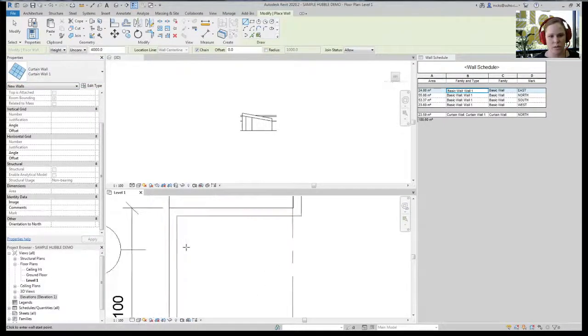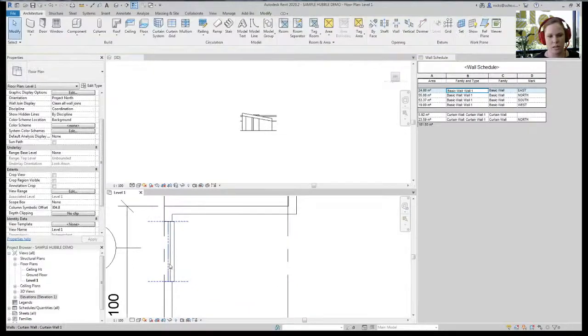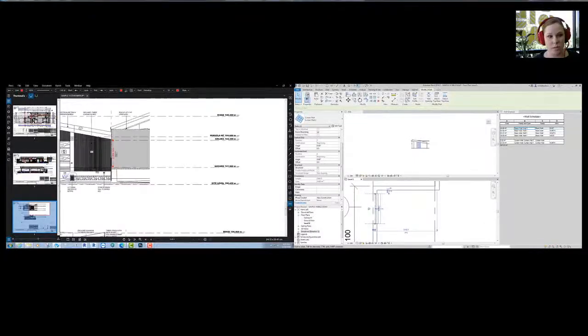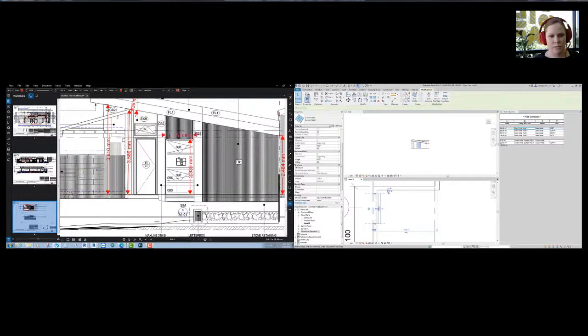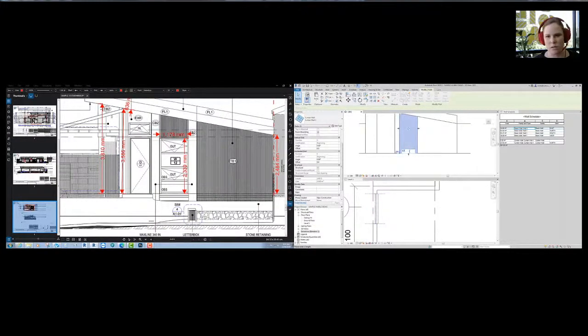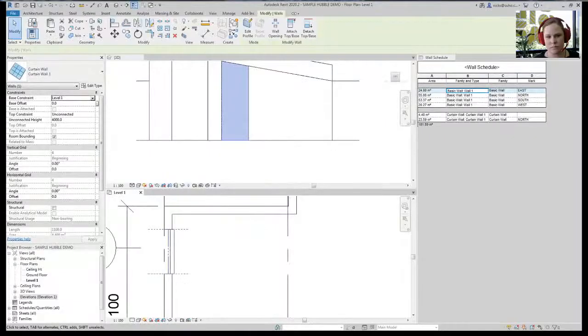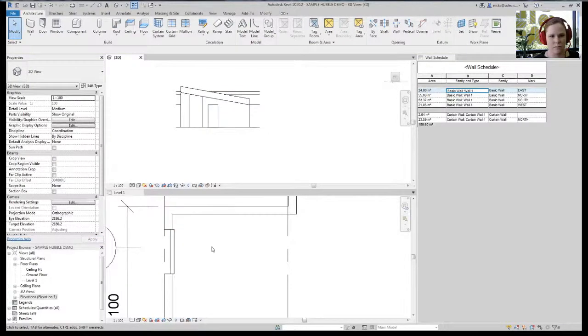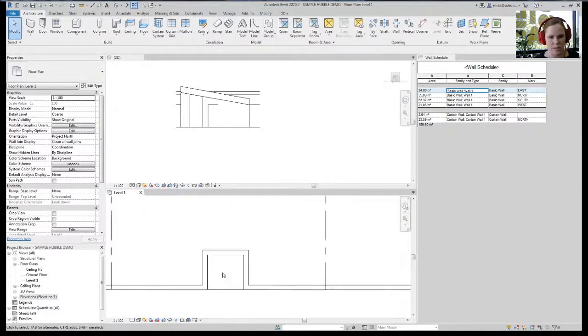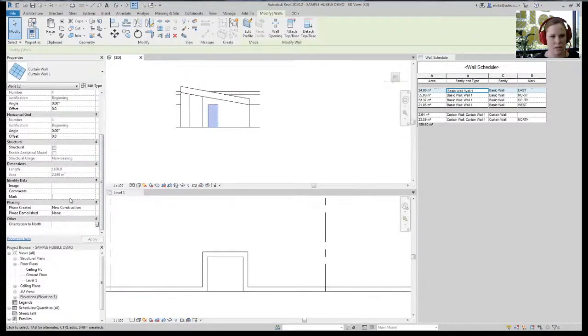Okay, so once again, putting in a curtain wall, which is essentially glazing, but it's just cutting into that wall. And again, just in terms of planning a site and a build, this is probably the quickest way to do it. This is 2400, so window. Height of the window as well. Let's just assume it's 2400. It's a little bit lower in the end because of the recessed blind out the front. Okay, and I'm going to say that that one is west. There we go, you can see the table on the right is updated.